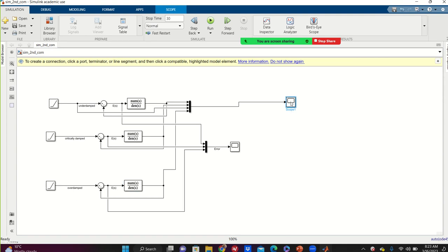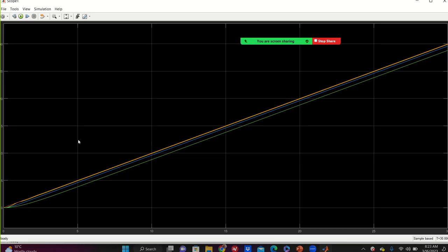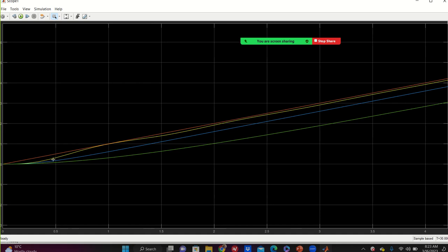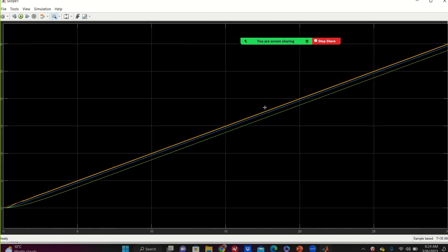And if I plot all of them for the ramp input, you see that I can make it big. This yellow line, guys, was for the underdamped system. This blue is for the critically damped system, no oscillation. And this is for the overdamped. You see that overdamped takes much longer time to settle down. And these are 2 zeta over omega.